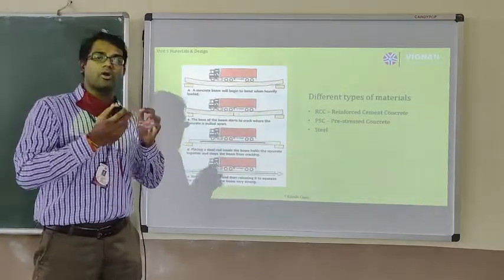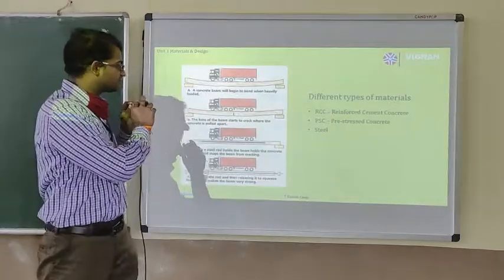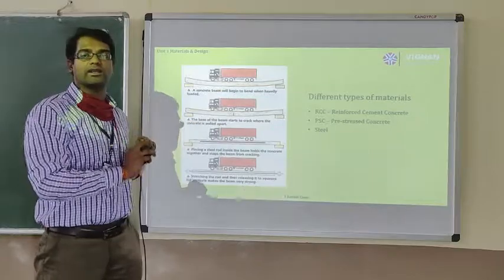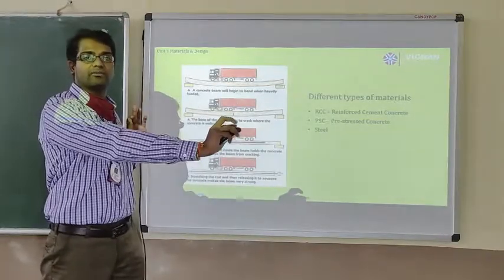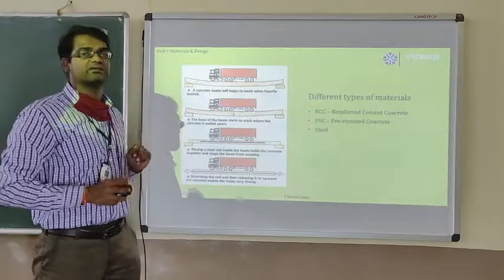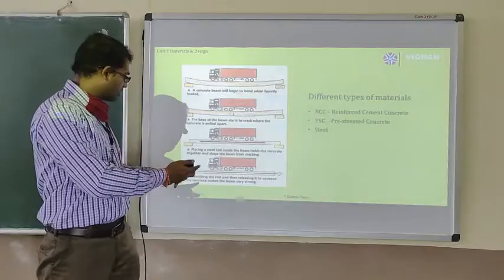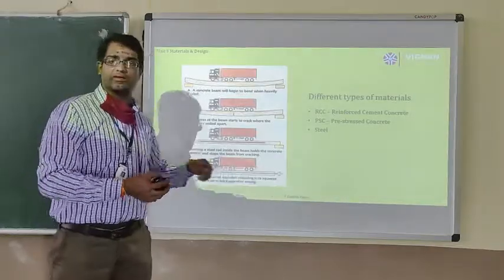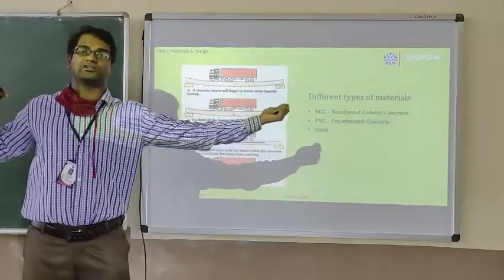Now in order to avoid the cracks in the concrete, we strengthen the cement concrete by providing these bars which we call steel bars. The concrete will be reinforced with steel bars. Now what if I remove the steel bars? I provide steel wire, not steel bar, steel wire, and I stretch it.